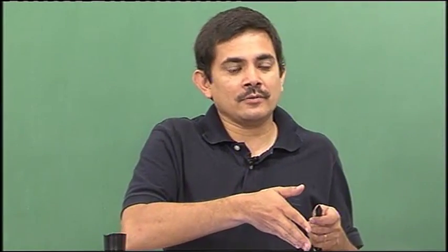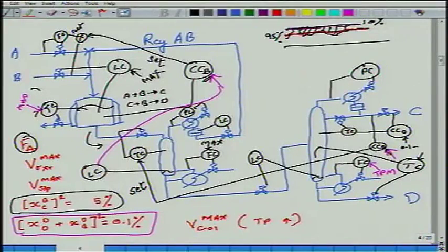If I do it the other way around, then this second constraint will become active earlier. Why will it become active earlier? Because it requires too much reflux. Yes or no? If it requires too much reflux because amount of D impurity is tight, then the boil up will have to be more, right? If the boil up is more, then it will get active earlier, throughput will suffer. Does this make sense or no? Right?